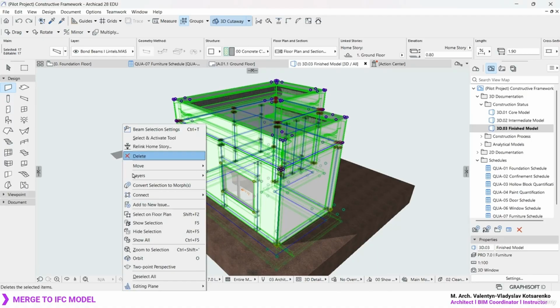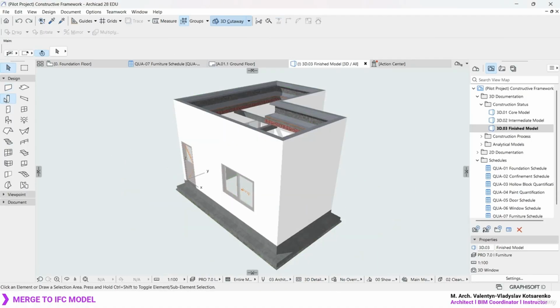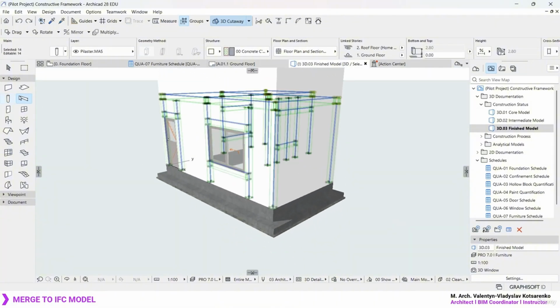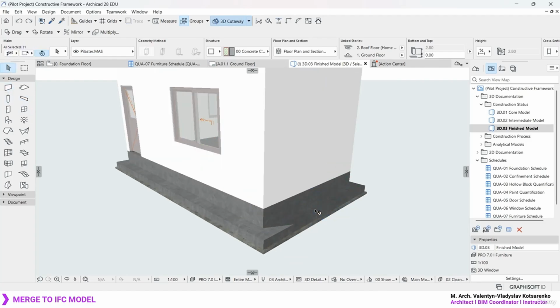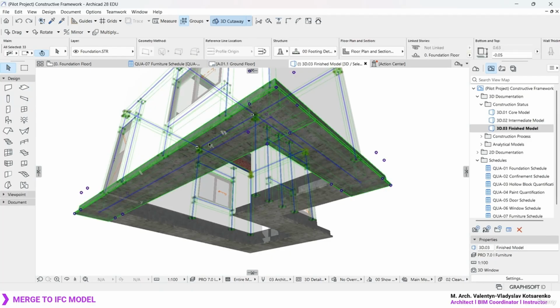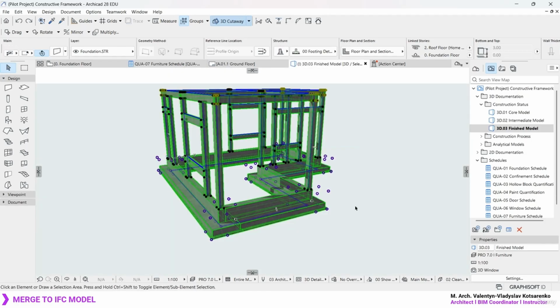Okay, sounds good. Show selection, and now I'll carefully filter out these once again really quickly. Select the tool, press Ctrl A, and then manually select only the foundation, which are also these elements we got over here. And let's filter these out, show selection.